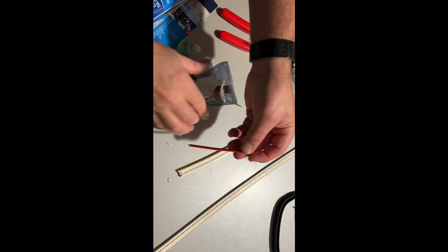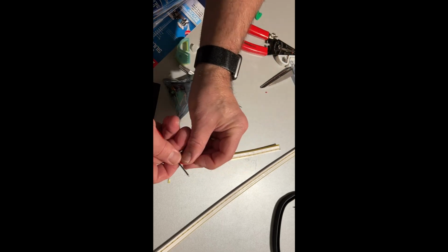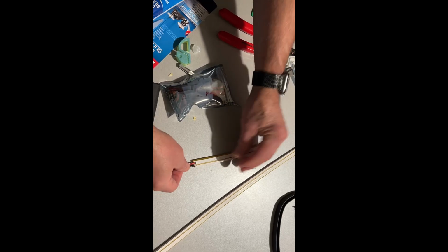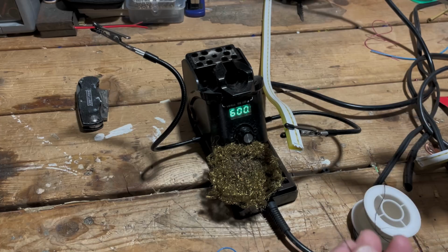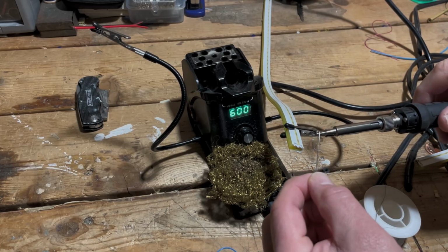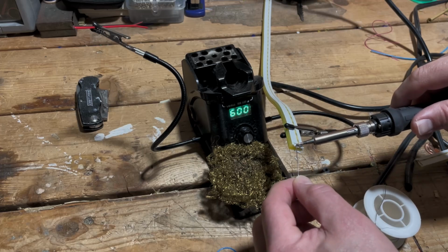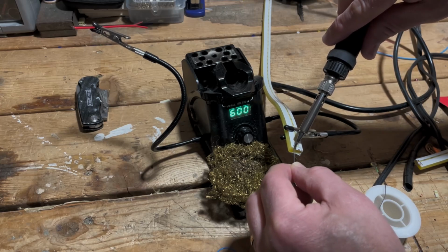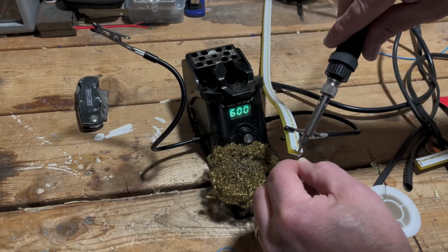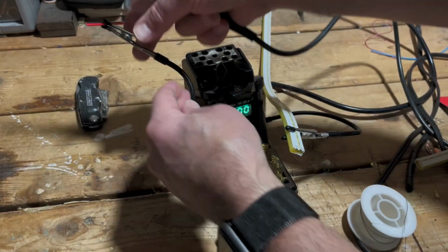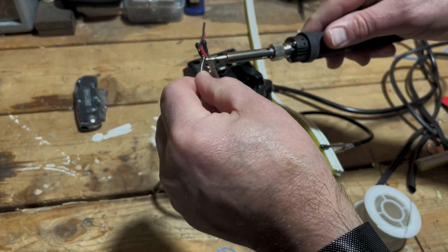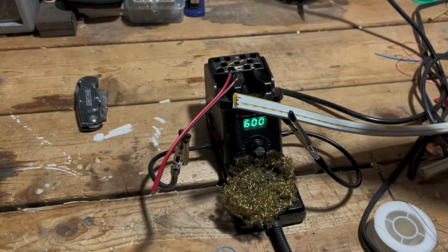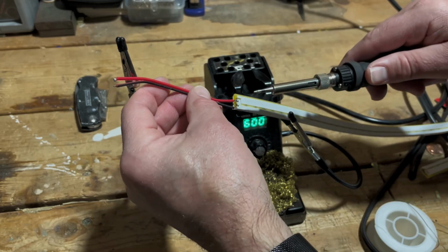Find the wires that come with the kits so that we can fasten these parts together. You'll solder the red one to the pad that has the LED facing up. All right, friends, so this is the basic soldering. Got it heated up, and I'm going to tin the pads. I am not an expert. Practice is making me better and better. You should definitely track down a how to solder video to make sure that you're doing yours as well as you can. We are also going to tin the ends of the wires so that way it's easier to solder them to the pads. I'll have a link to the soldering set in the description.